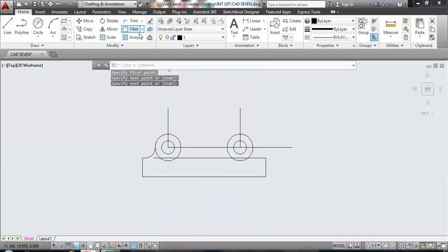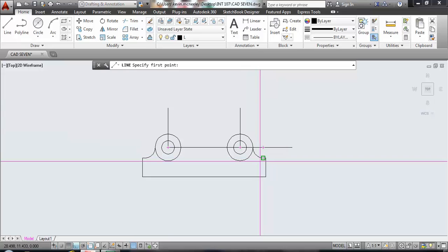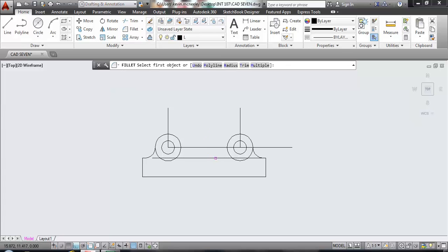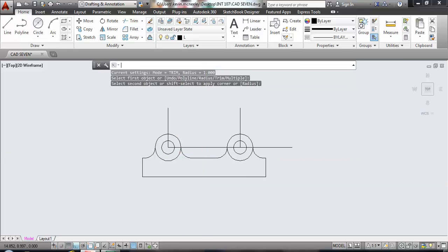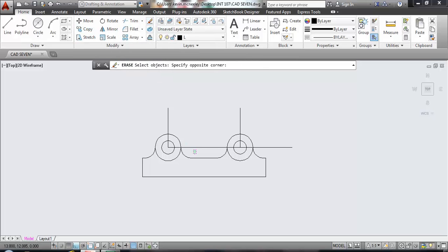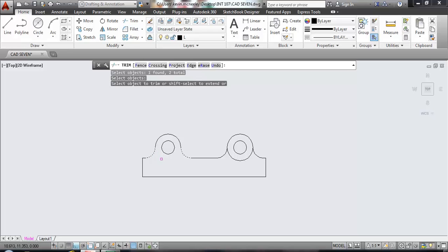And I'll use my Fillet command. Pick here, see it. Alright, now I'll draw another line from here over, trim, or Fillet rather. I'm going to go ahead and erase my lines that I have. And then I'm going to trim from this bounding object to this bounding object, enter, get rid of that, trim again, bounding object, enter, get rid of that.